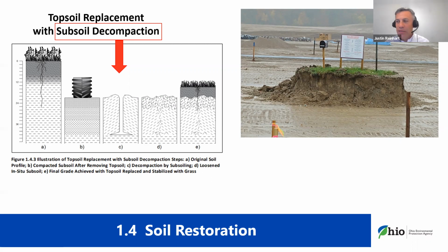But is that a problem? I guess it could be something to be taken into consideration, that this is a heavily trafficked, heavily maintained road area. Generally, what you'll see, if these are being used as more of a primary BMP, the areas will be much larger than the pavement. So hopefully that's not much of a concern. Or even that initial verge and grass filter or disconnection area up front can provide some of that treatment before it gets to the conservation area.